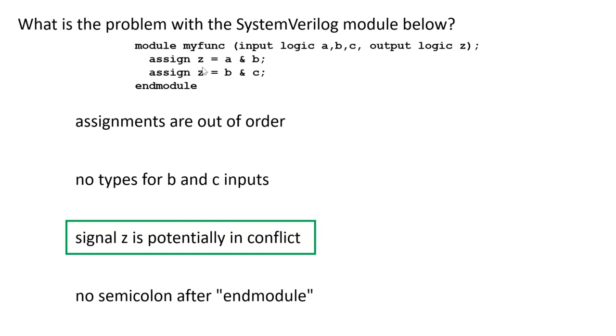Although in my experience doing that, at least on an FPGA, using Z high impedance is pretty rare. I'm not even sure how well that's supported on an FPGA, to be honest. So generally, you don't double drive a signal. You want to avoid that.